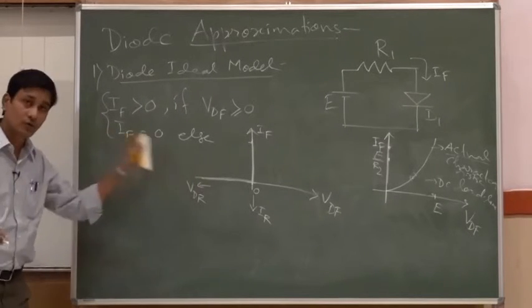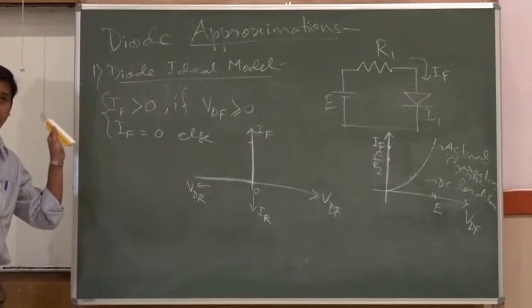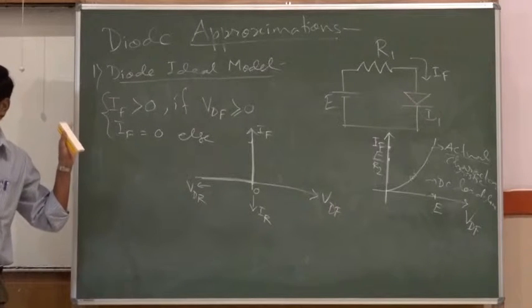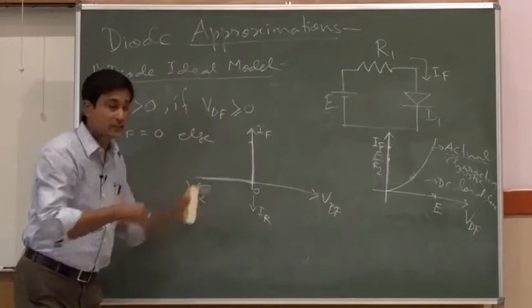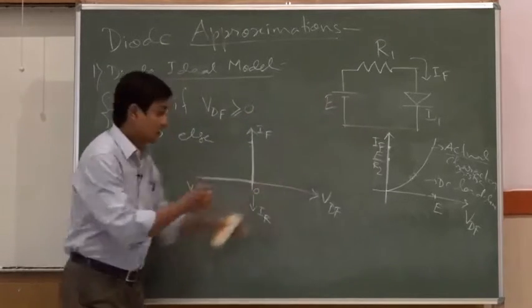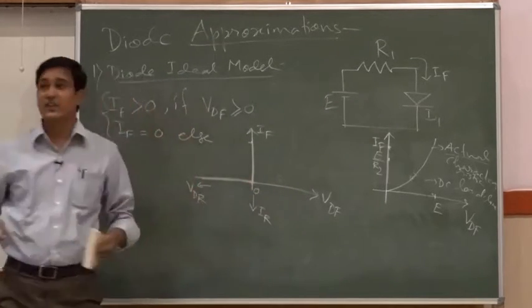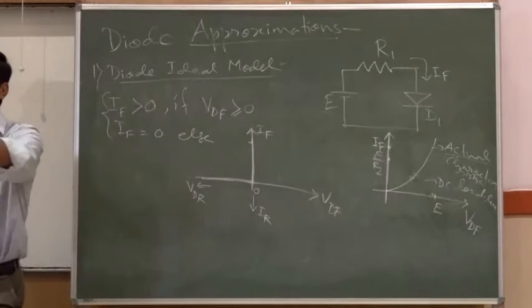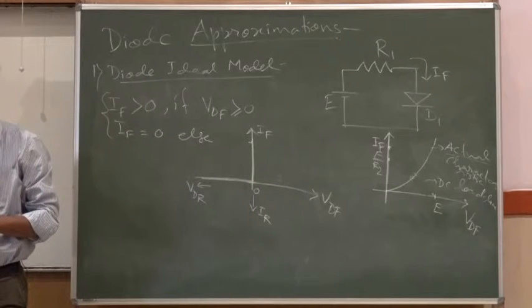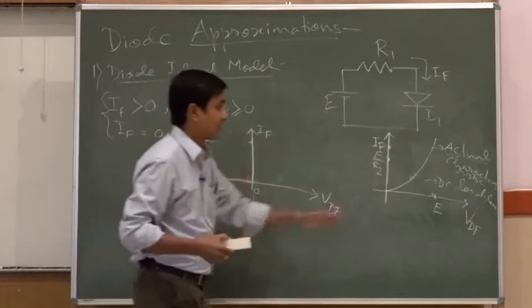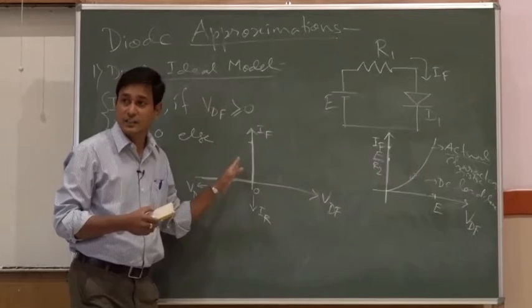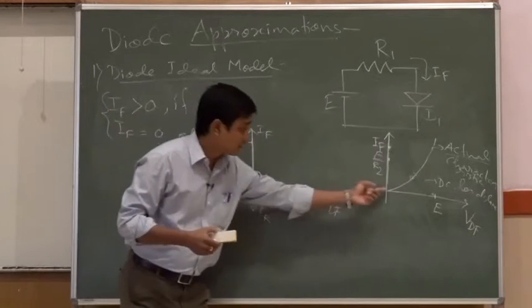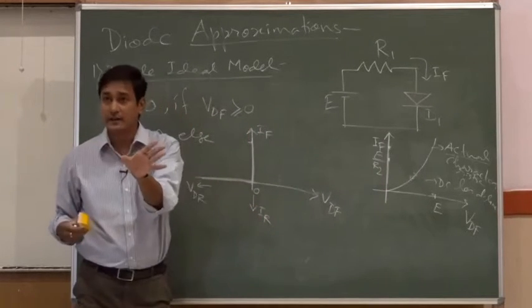It is going to the negative side, to a very high negative voltage, and from there you are slowly increasing the voltage, which is the negative voltage across the diode. The time it reaches 0, current will start flowing there. So, can I say that this characteristic is considered here in this form, considering that on the reverse side there is no current?